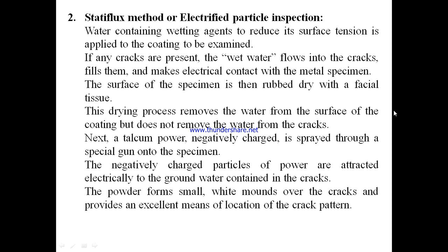The negatively charged particles of powder are attracted electrically to the grounded water contained in the crack. The powder forms small white mounds over the cracks and provides an excellent means of locating the crack patterns, which means that they will look like white lines.